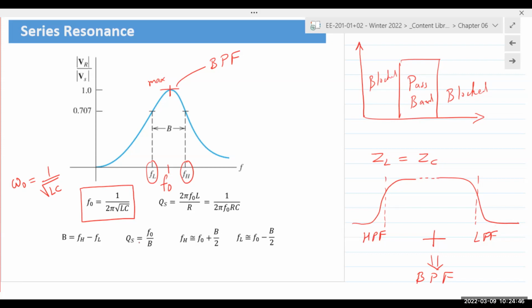But more importantly, we want that band to be as narrow as possible. In real life filters, as an example, if I want to tune my radio to 99.7 megahertz, I want only that frequency going into my device. I want the filter at the front end to block out everything else. In real life, it's never possible to design a filter that would allow only one particular frequency.